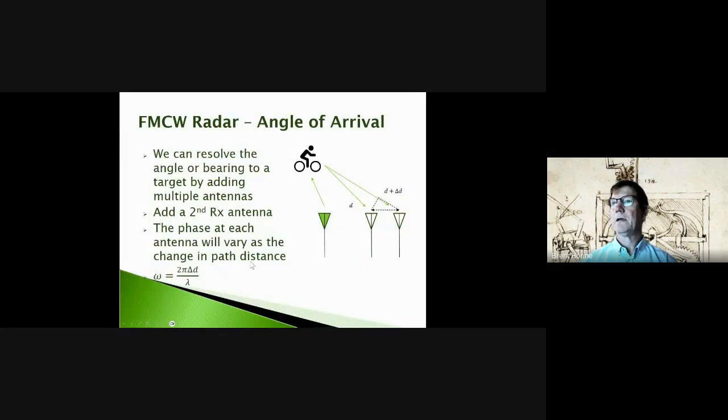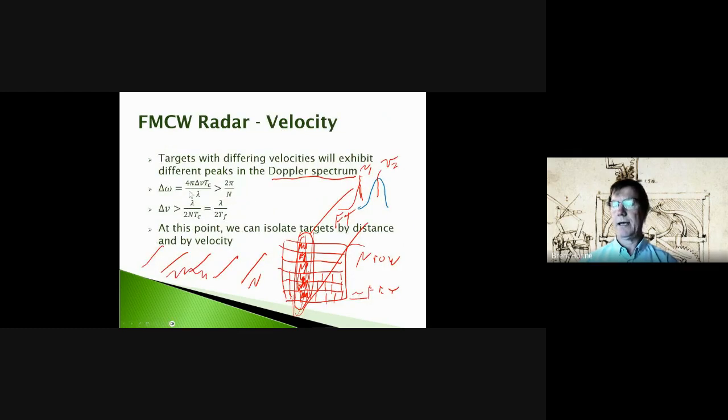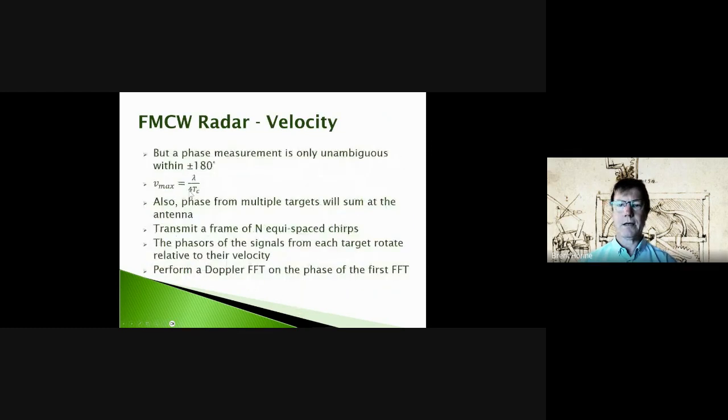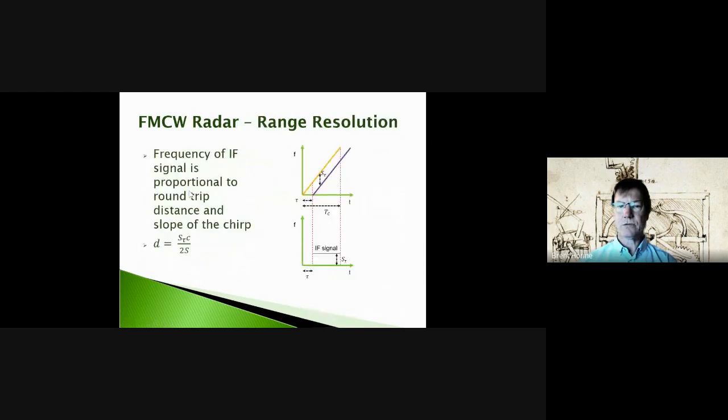Okay. I think we had covered distance with FMCW radars. Recall that when we say FM, that's standing for frequency modulated, kind of a fancy way of saying it's transmitted using a linear chirp, where the frequency varies linearly with respect to time.